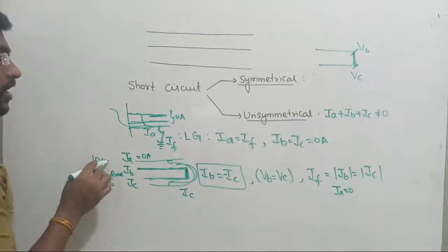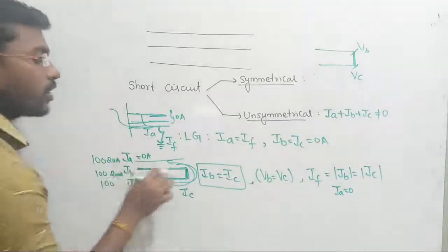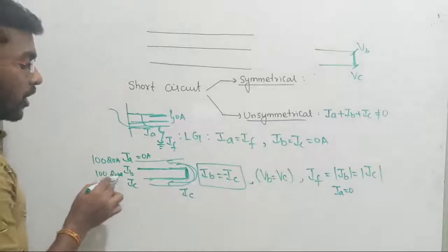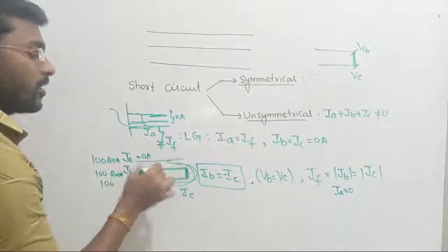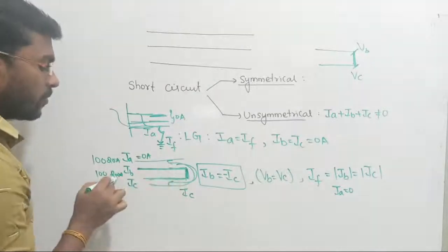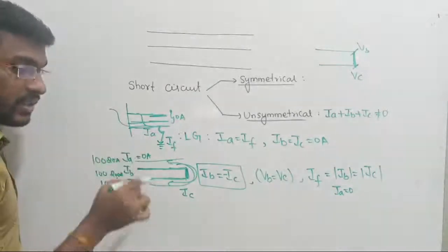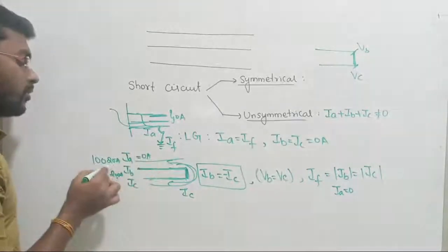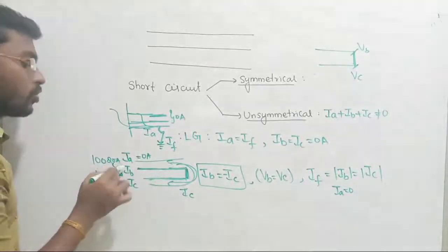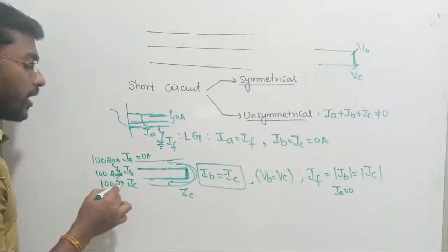Under that condition, if I assume that now through this transmission line a 20 ampere current is flowing, and through this 200 current is flowing, so 200 current is going in this, 20 ampere is going in this, see there, still I have some current here, but what has come here is only 200, right? But what I would like to do is worst case analysis. Worst case in the sense I am assuming this 20 current will also be diverted to the short circuit line, such that your circuit breakers are going to be designed for 220 ampere.